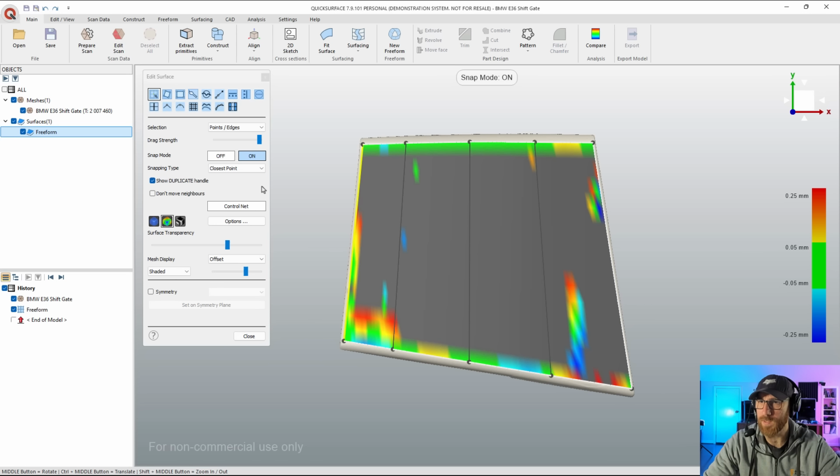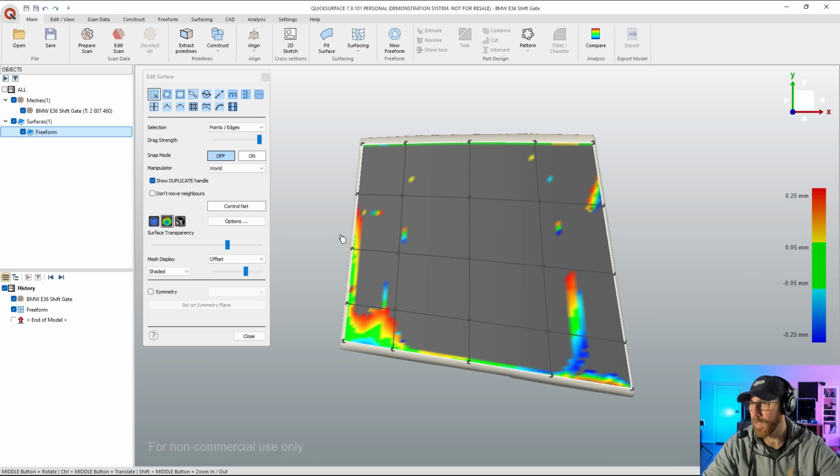So I'm going to do Control Z and undo, turn off snap mode, still select that edge and hit S and split it. I'm going to split it up here again, and I'm going to do it one more time. And again, it's going to sort of normalize everything. From here, instead of turning snap back on, what I'm going to do is shift select these 3 points, and